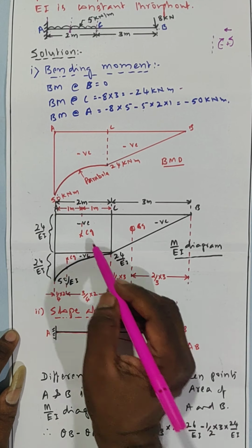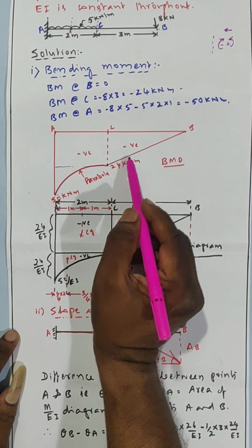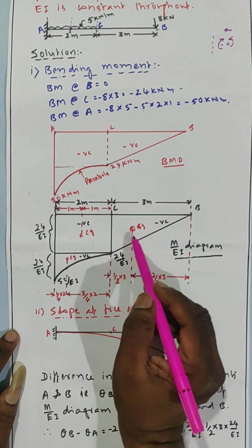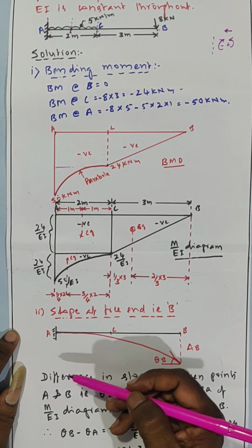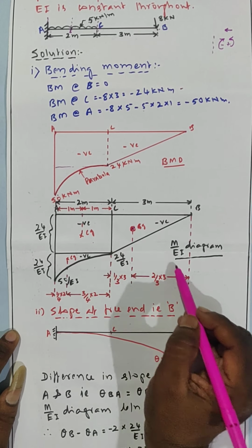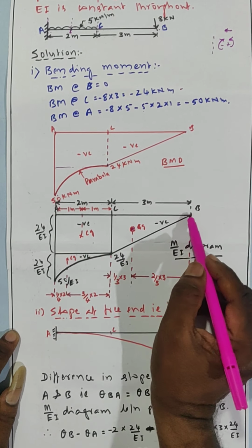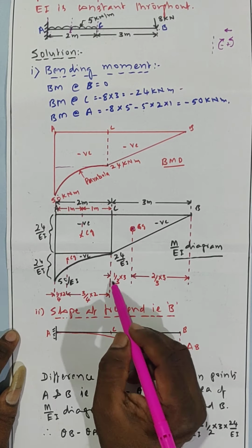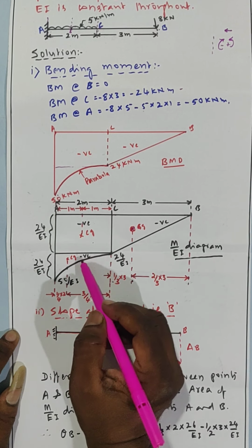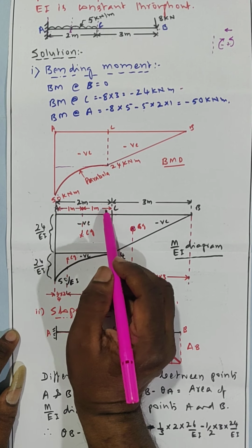Then for calculation purposes, I am dividing this area into one rectangle, one triangle and one parabola. I made 3 sections. For the triangle, the CG is here, at a distance of 2/3 of this distance 3 from the apex, which is 1/3 of 3 from the base. It is shown here. Similarly for the rectangle, we know it is at the center: 2 meter means 1 meter.